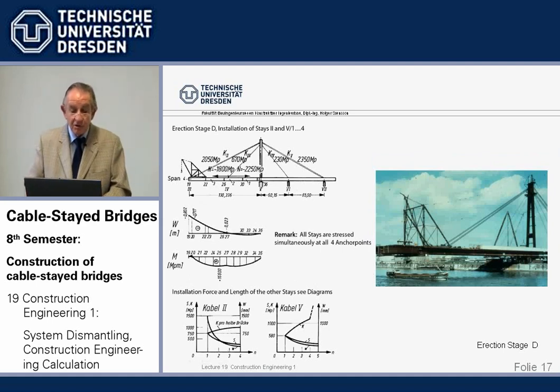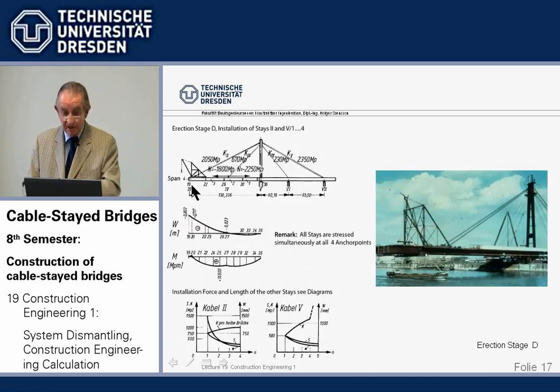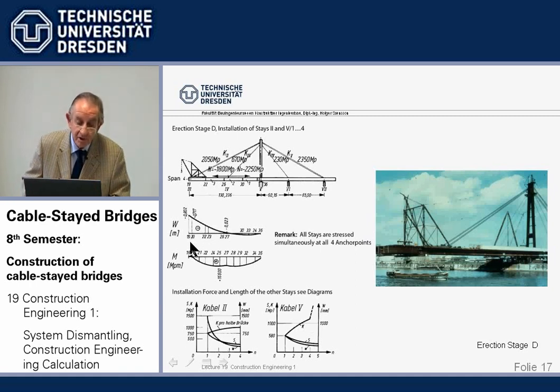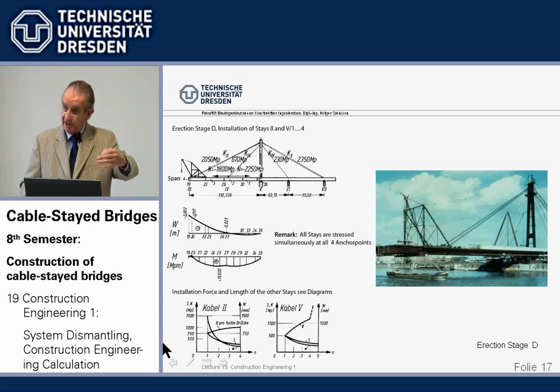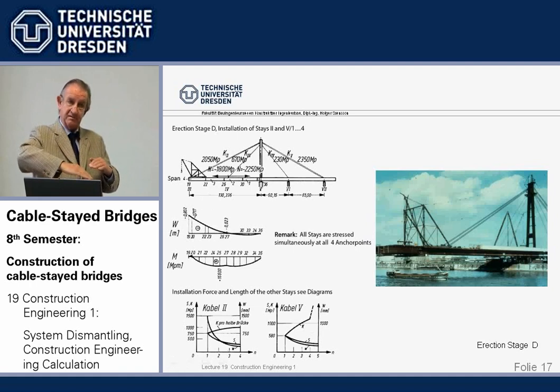Now, we have now installed, the difference between the two is, here we have cantilevered the beam, but the cable isn't in. Here we have just installed the stay cable, we haven't done anything to the beam. So, what happens with the tip? From 1.88 meters down, before a cable installation, we are now 0.8 meters up. So we have a movement of 2.6 meters during cable installation, up 1.8, up 0.6.